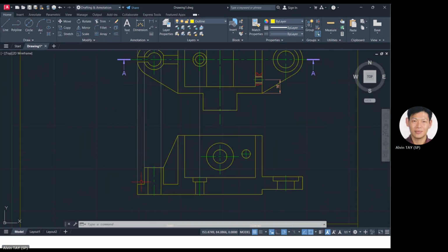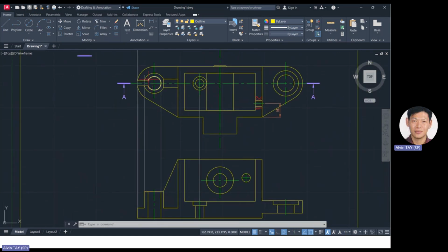I can still see this line, so that's why it's still solid line here, solid line here. The 10 mm width here to here is a web. So the shape of the web must remain intact. We're not going to section this.